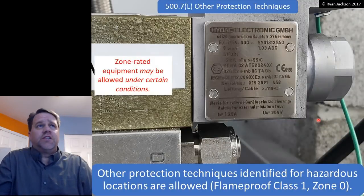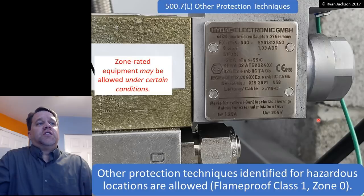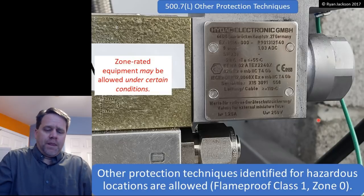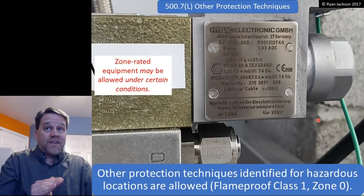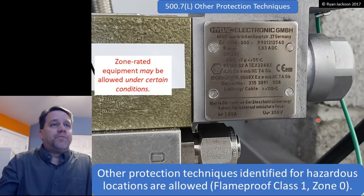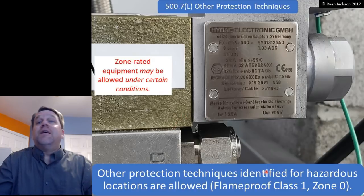The last protection technique is subsection L, other protection techniques. Other protection techniques that are identified for hazardous locations are allowed as well. The code doesn't tell us what these might be, but an example might be zone-rated equipment that is specifically identified for use in a class division location. So zone-rated equipment under certain conditions could be used, like flame-proof equipment.